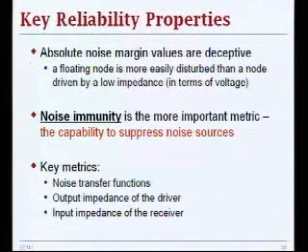If you have a high impedance, what does that do to your voltage? It's very unreliable, so you can drive that signal away from its desired value. So obviously you would want very low impedance at that node so that it really exhibits the properties of a voltage source and provides a really good solid voltage at that node.